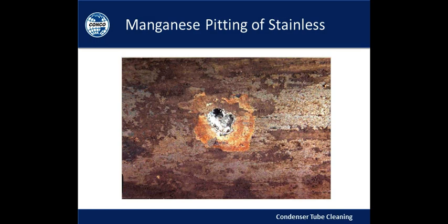The manganese is on that tube wall because there was a substrate of bacteria or a biofilm to allow it to collect. So without the biofilm, you've got no manganese scale deposit. This manganese should wash right through the condenser tubing, but the presence of the biofilm allows the mineral elements of manganese to stick to the tube wall. As it accumulates, it's then affected by temperature and scales up.